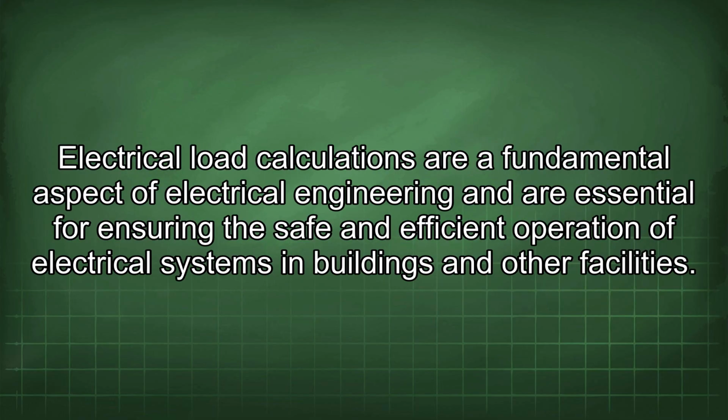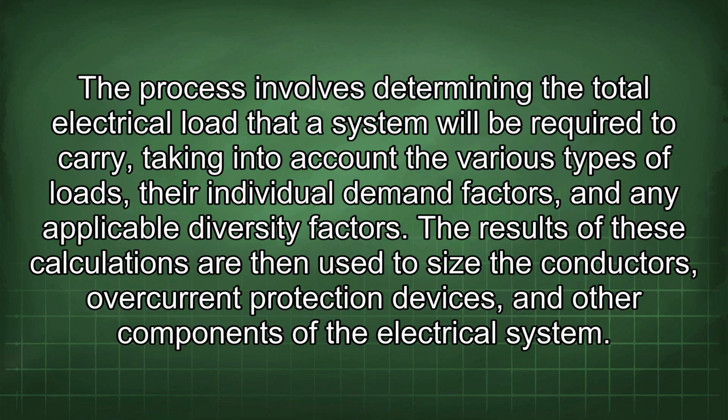Electrical load calculations are a fundamental aspect of electrical engineering and are essential for ensuring the safe and efficient operation of electrical systems in buildings and other facilities. The process involves determining the total electrical load that a system will be required to carry, taking into account the various types of loads, their individual demand factors, and any applicable diversity factors. The results of these calculations are then used to size the conductors, overcurrent protection devices, and other components of the electrical system.